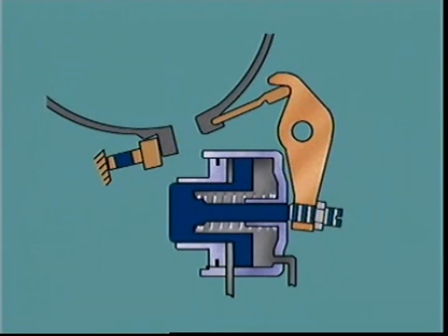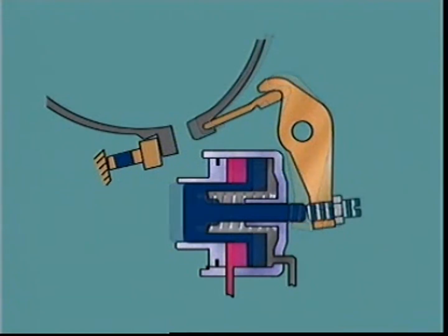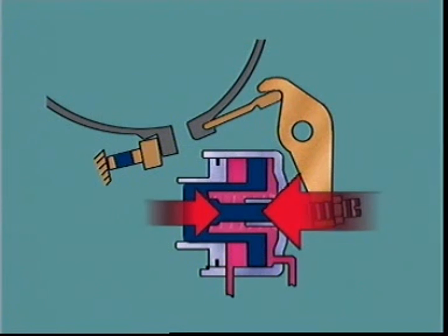Pressure release servos can also have pistons with unequal areas. In this case, the release side has a larger surface area than the apply side. The band is brought into operation by directing fluid onto the reduced area that surrounds the hollow portion, accommodating the return spring. When fluid at the same pressure is directed to the release side, the differential area results in a higher release force.